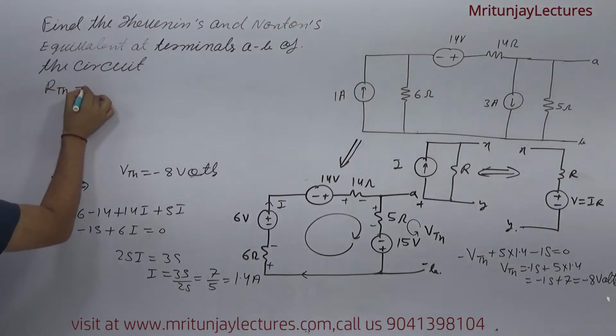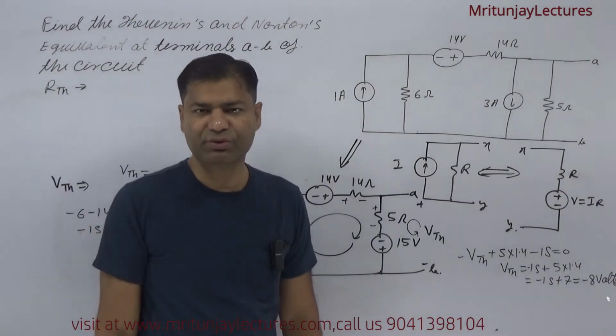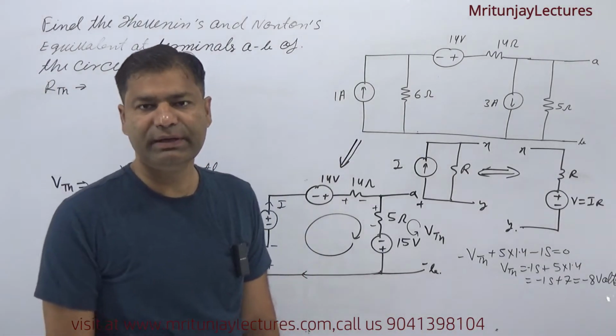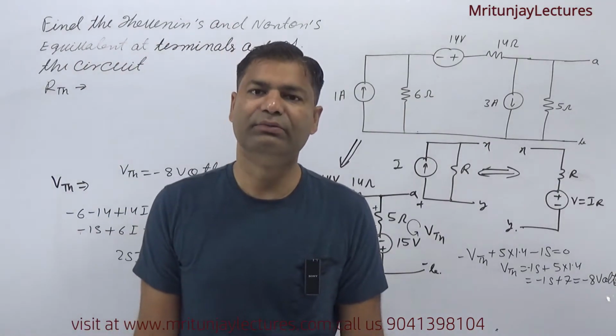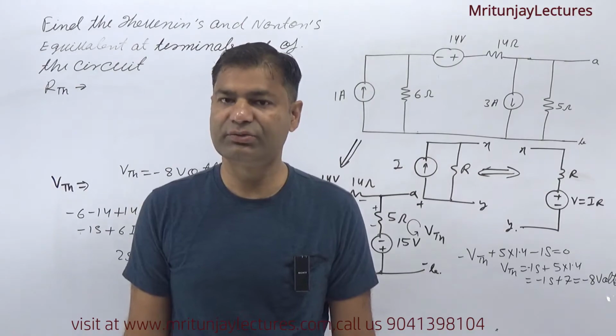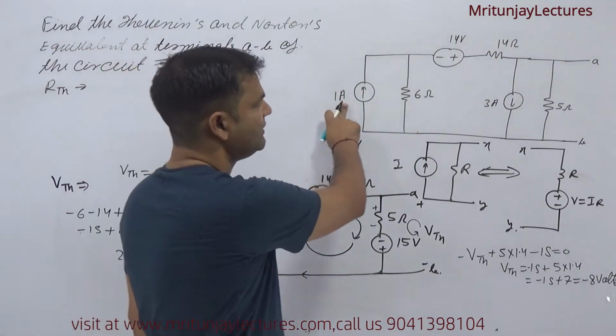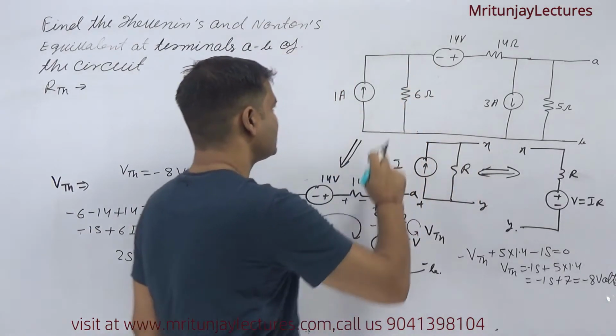If you determine RTH, all independent sources are reduced to 0. Independent voltage sources behave as a short circuit and independent current sources behave as an open circuit.